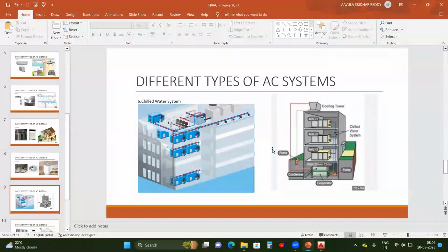So we will take the chilled water system. The chiller, cooling tower, everything set up, we will place somewhere on top of the terrace, and we will connect the chilled water pipe with all units. So the outdoor unit will be only one, that is the chilled water system. You will understand this better in the chiller topics. So consider till here, you can imagine that instead of outdoor units, if we want to attach more indoor units, we can go with the chilled water system.